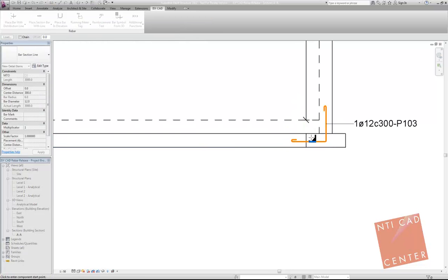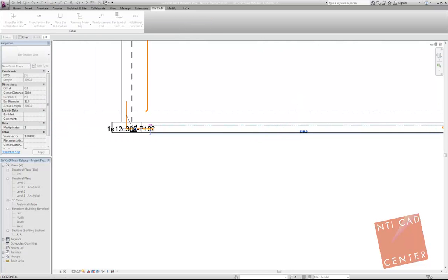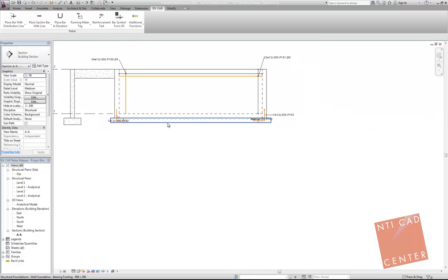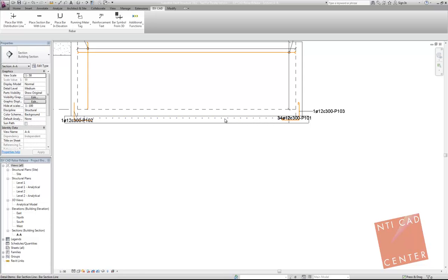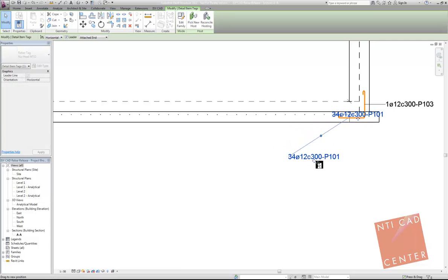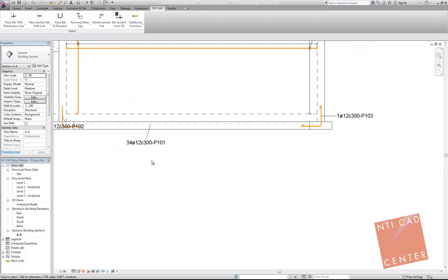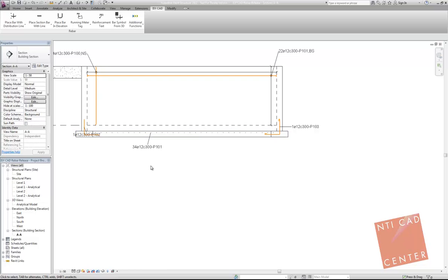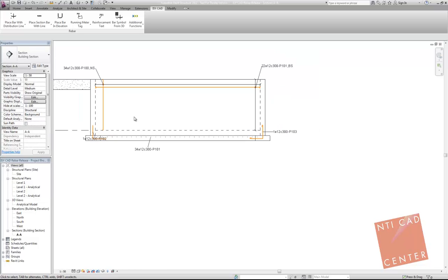Then I just need to specify the location line of the elements, and I will have all of the rebar placed here, shown and tagged. Again, further on, I can select this tag, which is showing the rebar. Maybe I can place it somewhere else and say, okay, free end, indicate this bar, for example, or so on. So there are possibilities to specify the rebar.